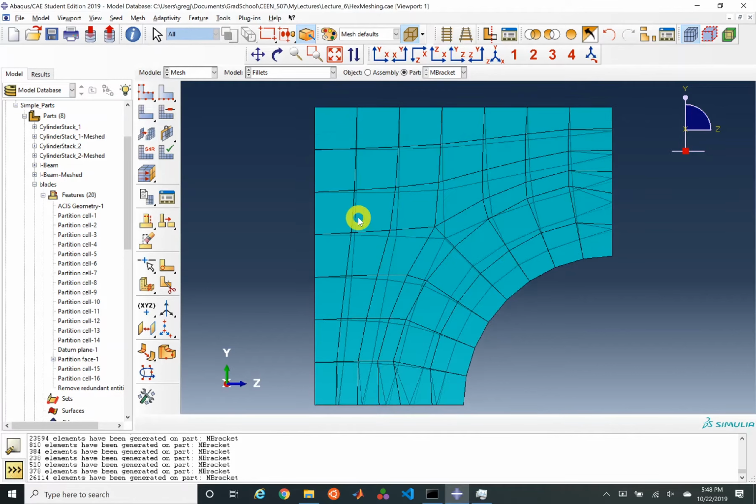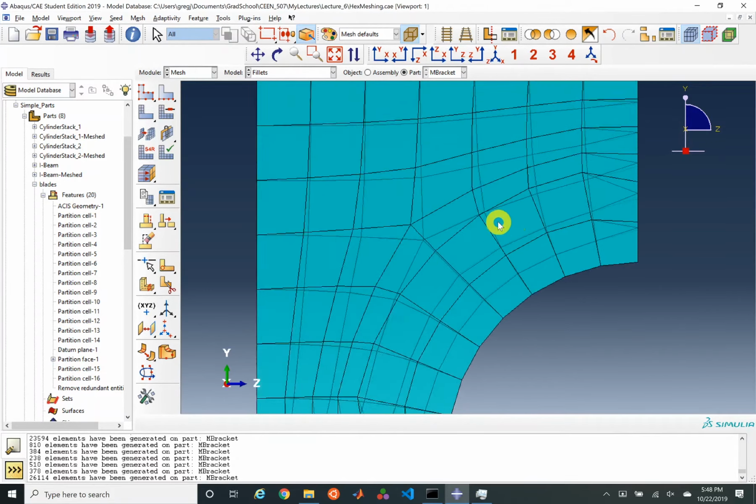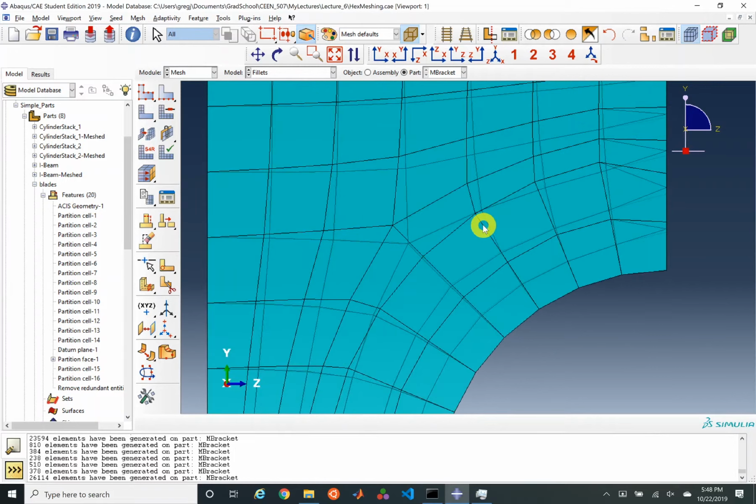And so what you can see is that some of these nodes aren't lining up. As opposed to a merged mesh where, between elements, all of our basis functions are C0, which is what we've traditionally been doing, now we've got nodes where they're discontinuous. They don't match up. They're not continuous at the element nodes.